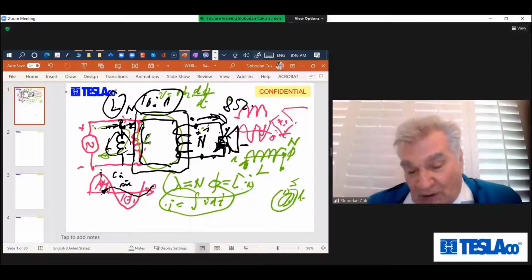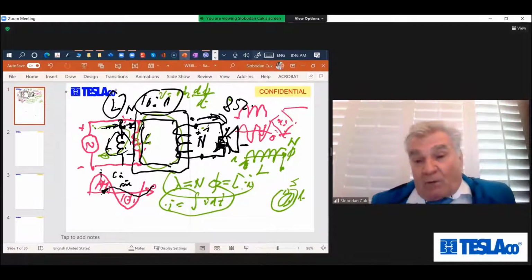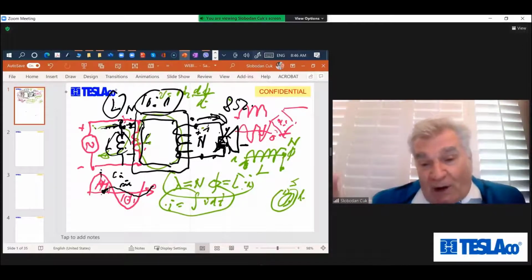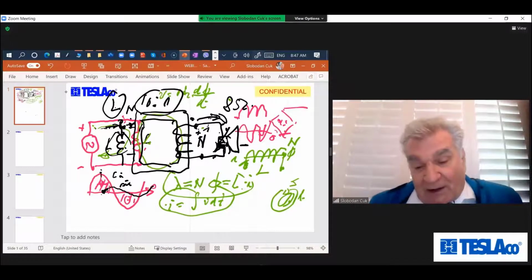But is that used in the switching converters? No, because we often do one wrong thing: we think what's important is to use a duty ratio of the converter down at 0.1 so we can step down with the duty ratio. That's wrong. If you do that, you're going to be stuck with high voltage devices on the primary and high voltage devices on the secondary.